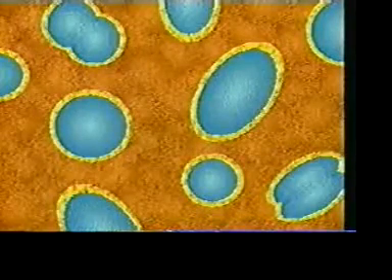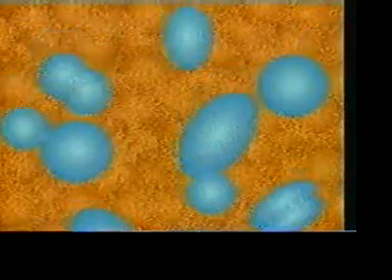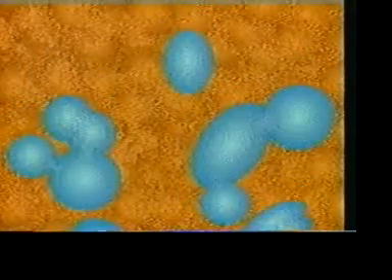In order to break an emulsion, the film surrounding the droplets must be neutralized or destroyed by using treatment methods. Treating in the field can be done with equipment such as free water knockouts, separators, heater treaters, and electrostatic treaters. Treating also includes adding chemicals to an emulsion immediately after it's produced.